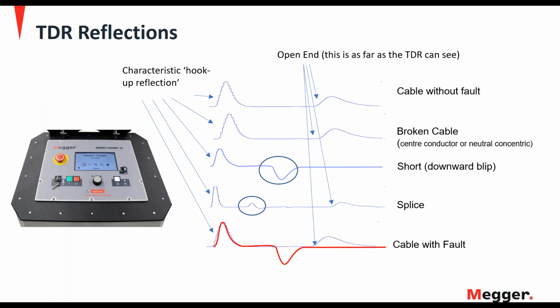And then finally, down back to the bottom, the cable with a fault. This is where we use the thumper to create an arc. The radar reflected off the arc. We display it in red to indicate it's a high voltage reflection. And of course, the fault distance is right here where the separation point is.